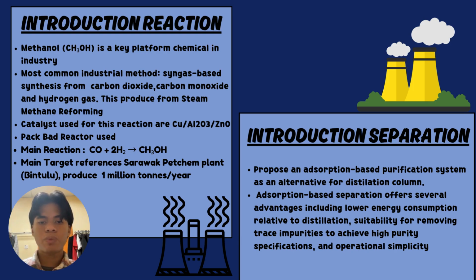The second one is the introduction for separation process. This proposes an absorption-based purification system as an alternative to the distillation column. This absorption-based system has advantages including lower energy consumption relative to distillation, suitability for removing trace impurities to achieve high purity specification, and operational simplicity.